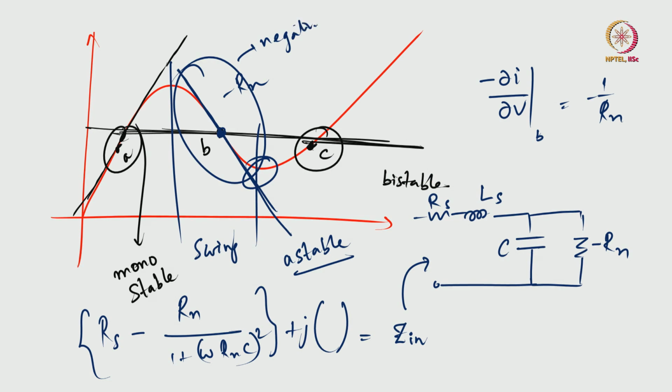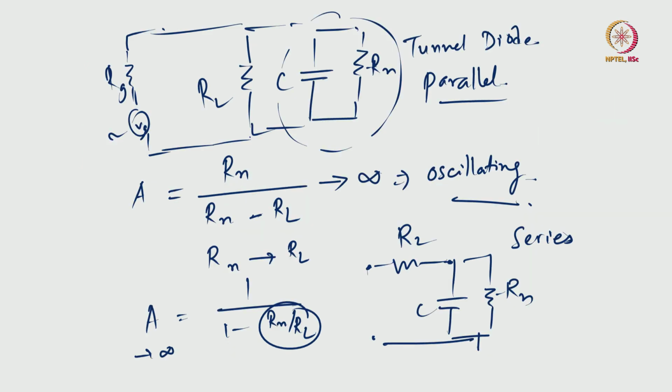The voltage swing around that point is actually quite low, because this region is quite low. Because of this low voltage swing, the RF power that you can get is also quite low, and that is why they are not very commercially successful, in the sense that your voltage swing is low and so your RF power is very low. To compensate for the low voltage, you can have a very large area diode, so that the current can be very high to offset the very low voltage swing.